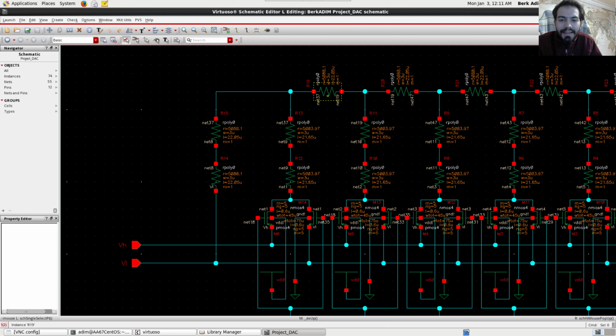If you have the same width and the same length, you are going to get higher on-state resistance for PMOSes and lower on-state resistance for NMOSes. I actually discussed this with a professor recently, and he told me that in modern processes such differences are not there, there is no difference in charge mobilities, but we are using a fairly old technology here.